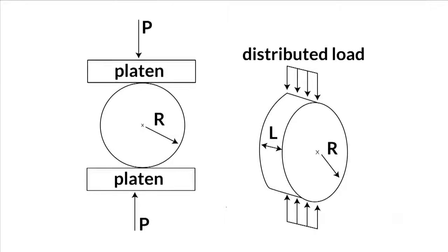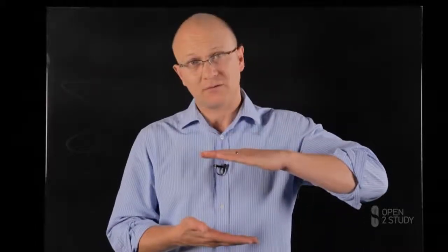And what happens, you can see on this picture, the cylindrical specimen lays flat on its curved surface with the flat surfaces being vertical. And the specimen again is placed between two platens. And as the load is applied, this load is distributed along a line on the curved surface, and that splits the specimen in 2 halves as the load is increased, as you can see on the video. You might wonder why this compressive action on the specimen might give this information about tensile strength of the material.